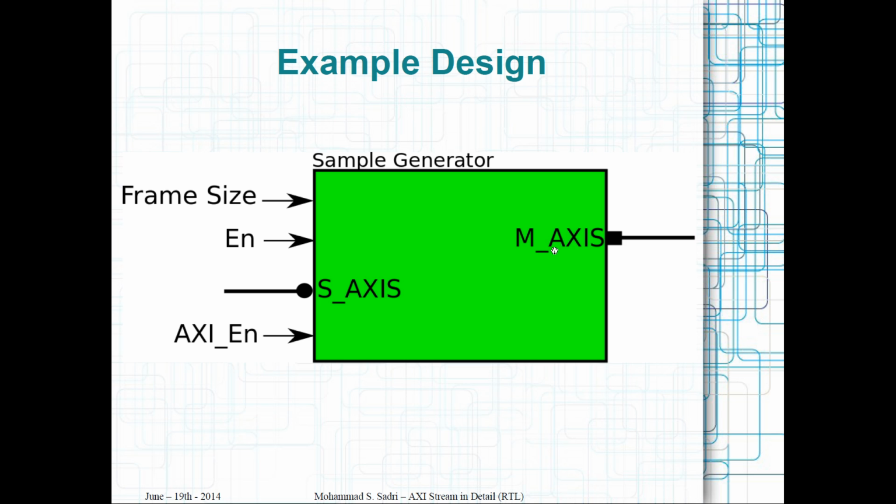I will introduce to you for the AXI interface that we have here a new signal that is called T-last, and this T-last is an indicator of the end of each frame, because in many situations the data that you transfer between AXI stream modules is grouped in frames.